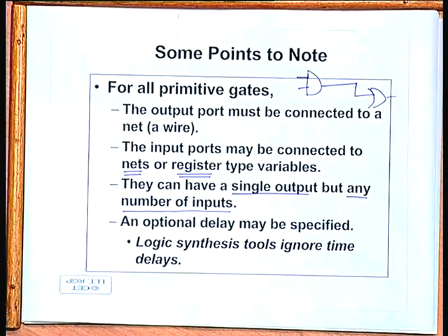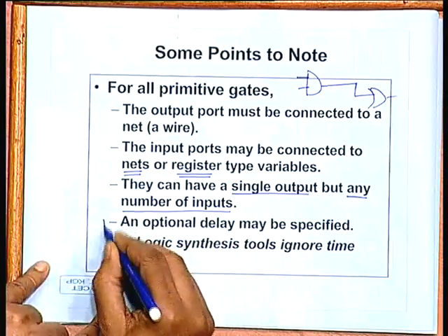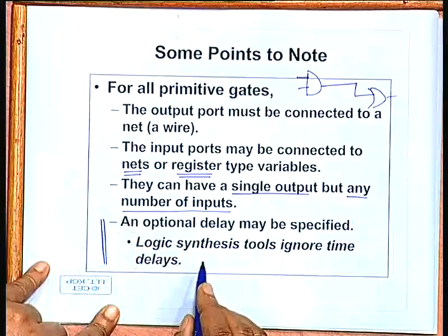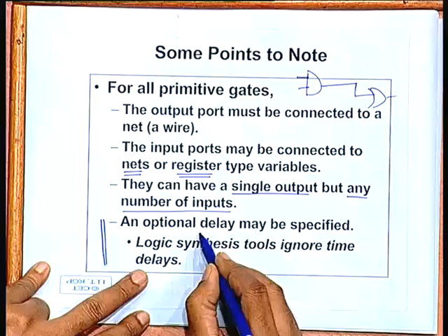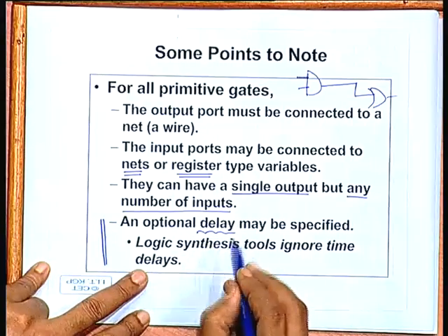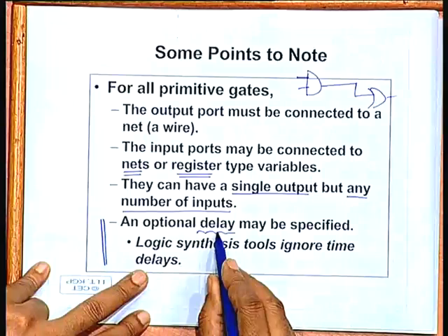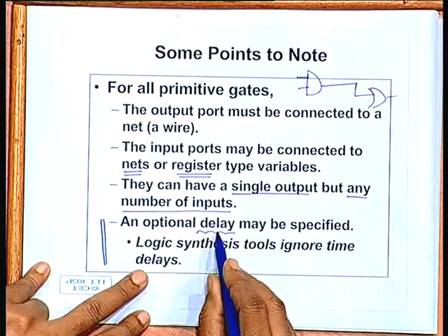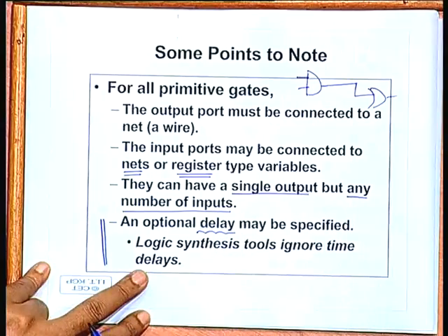And as we shall see, this is again used solely for the purpose of simulation, not for synthesis, that you can specify a delay with each gate or with each component you use in your design. Once you have this delay specified, then you can interpret your result of simulation, that after this much time the output should change state. You can see the timing diagram, for example, and see that it is really changing after that time, right.